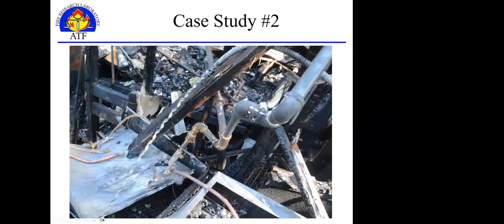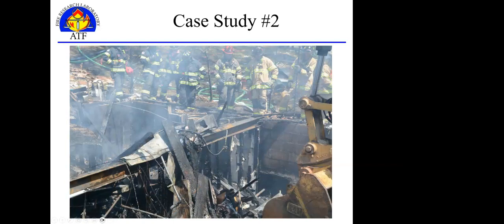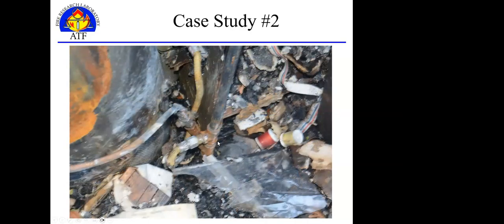So here are the witness marks that I placed. This is coming down to the furnace, I believe. Just another showing that here's that 90 from the gas line, and the 90 follows here. It had broken just above this I-beam, and that might have been because of the excavator. He was a good excavator operator and didn't do a whole lot of damage, but I think just clipping that line was enough to break it.